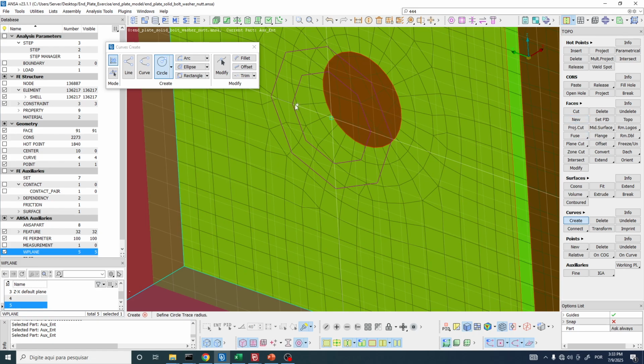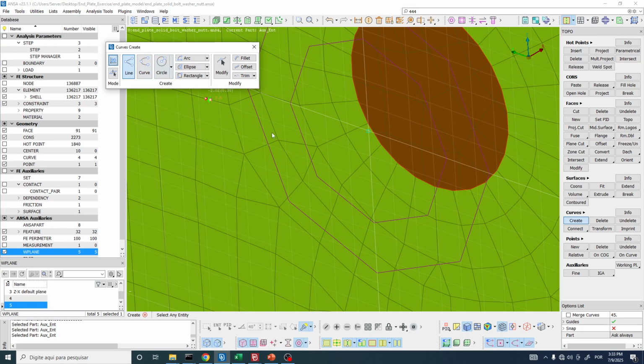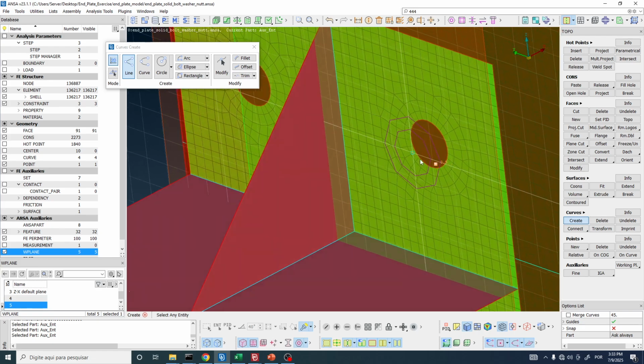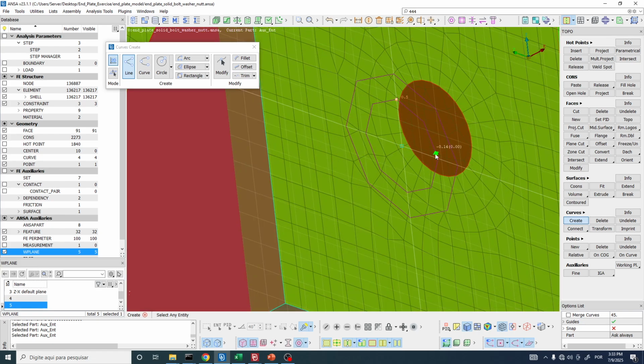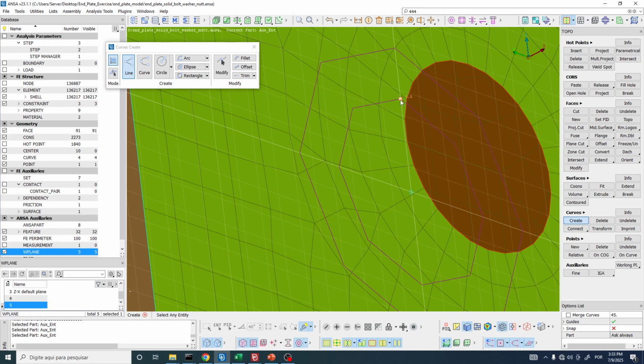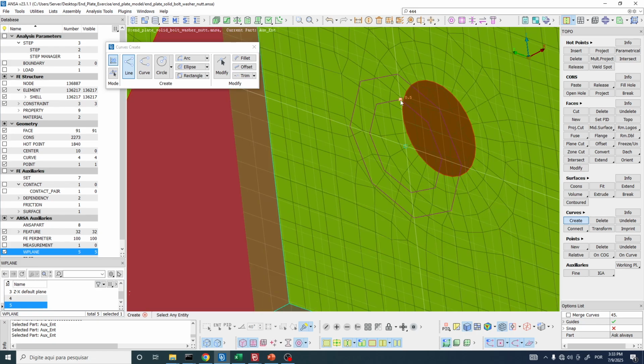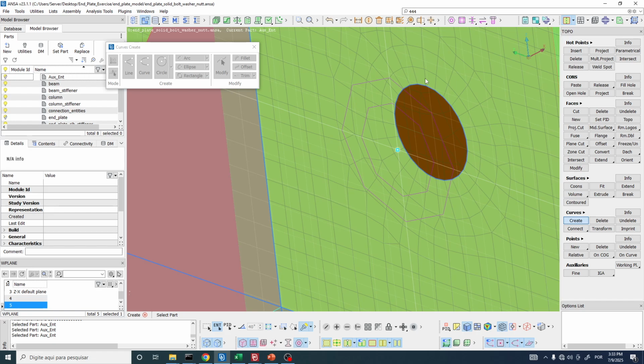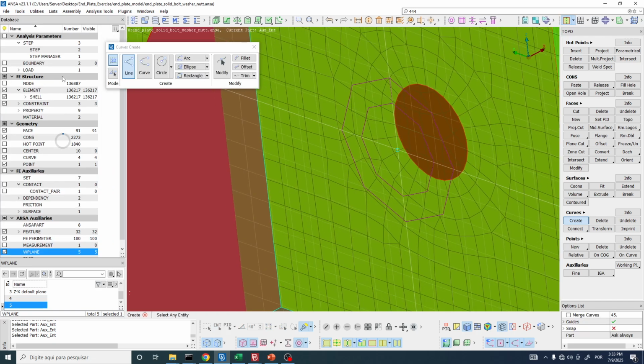So what we need to do here is to use the line tool and close. And well, we have this snap here of 0.5. Find this snap of 0.5 here. Left click and go to this other curve, and also find this snap of 0.5. And then middle mouse button to conclude and put in auxiliary entities.